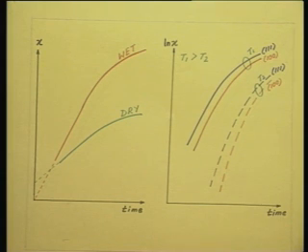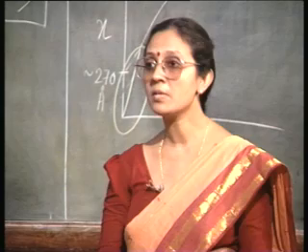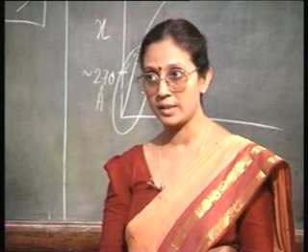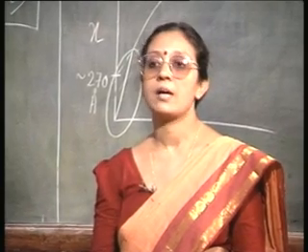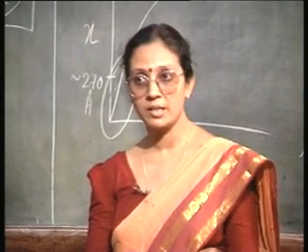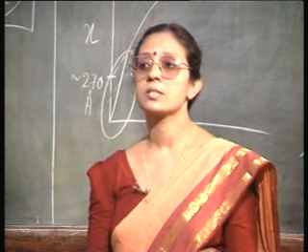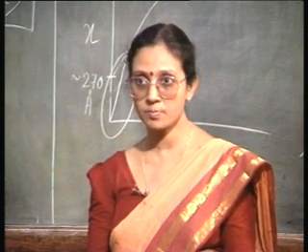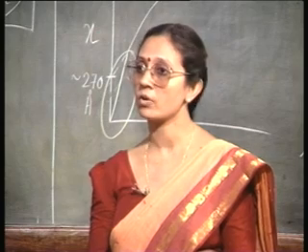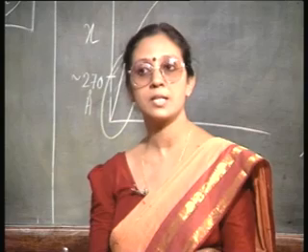However, as the oxide grows in thickness, the oxidation enters the parabolic regime from the linear regime. And then the advantage of having a larger number of silicon atoms is somewhat lost, because the oxidation is dependent more on the diffusion of the oxidizing species, because already a thick enough oxide is grown. So, it depends on the availability of the oxidizing species.